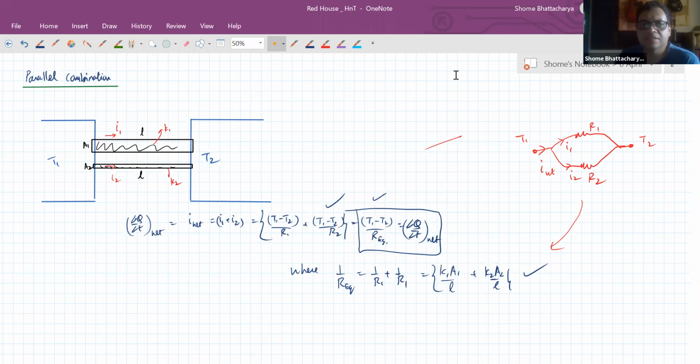No, Ansh, it is not necessary always that in parallel the lengths will be equal. The type of shape I have drawn, it was necessary here that the lengths are equal. But the heat reservoirs can be shaped in a different way, no? So that the two interfaces are not parallel to each other. So in that case, the lengths could be different. So when you do 1 by R1 plus 1 by R2, you'll have different values of L1 and L2 in that formula.